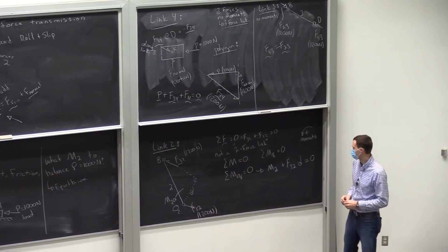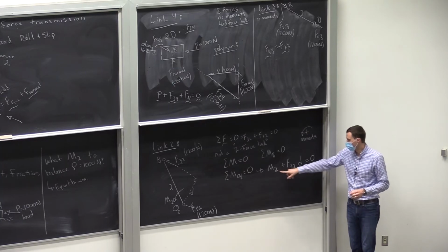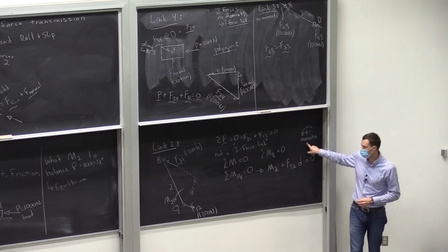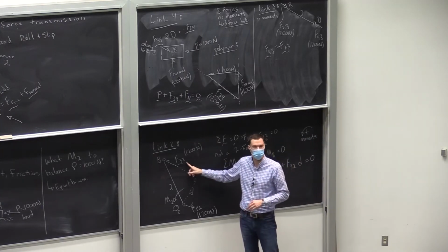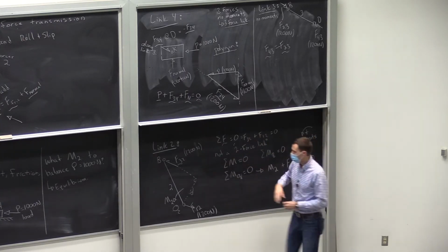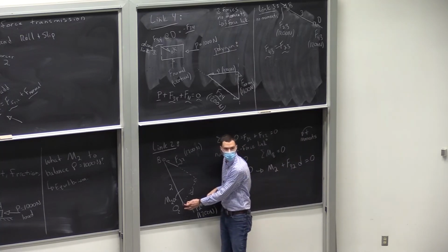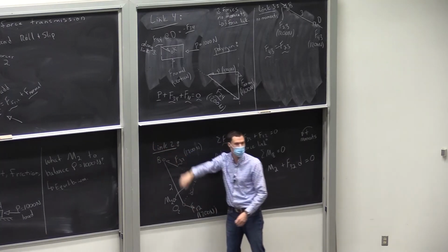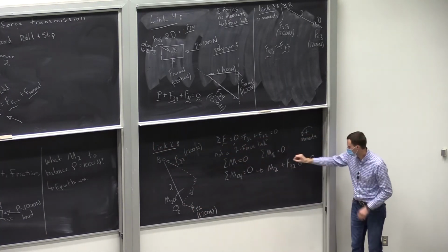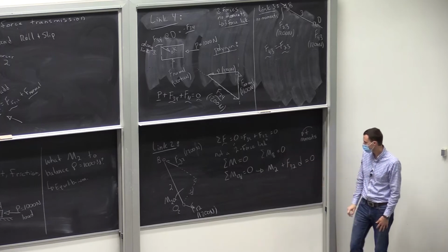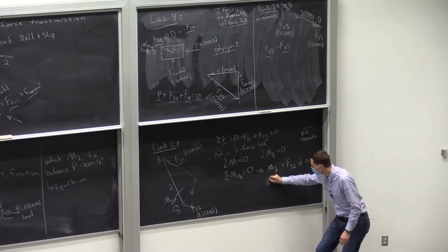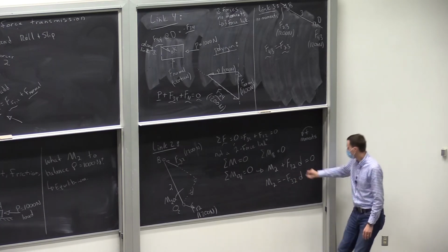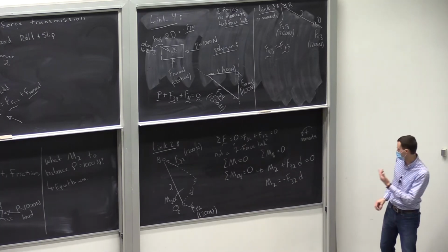Before we solve for it, did I get the direction right? Positive is counterclockwise. So is F32 causing a counterclockwise or clockwise moment about the base point? It's pointing this way, about this point, so counterclockwise. So plus is good. Now we can solve for M2. Negative F32 times D. So we just plug in our numbers.